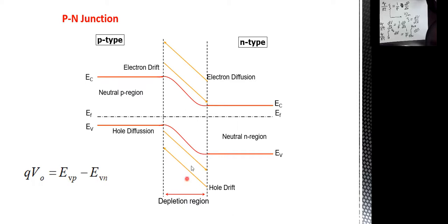What I mean by carriers is either free electrons in the conduction band or free holes in the valence band. Accordingly, this region will turn out to be a region depleted of carriers. That's why we call it the depletion region. And this is actually a very important point in what's called the capacitance of a p-n junction, which will be the last slide in this lecture.